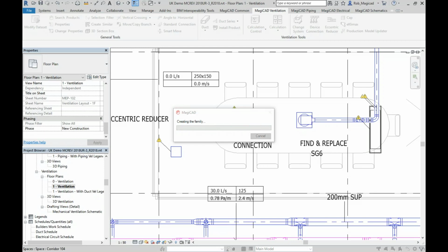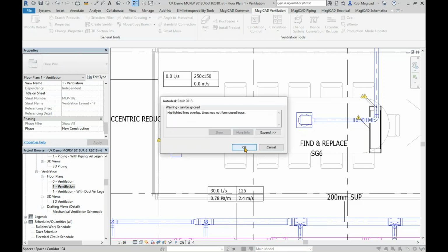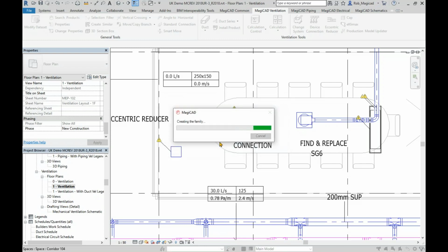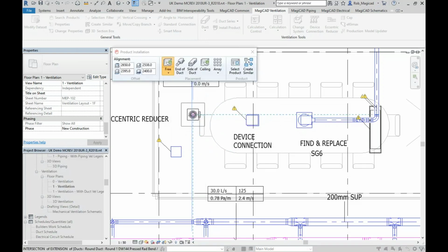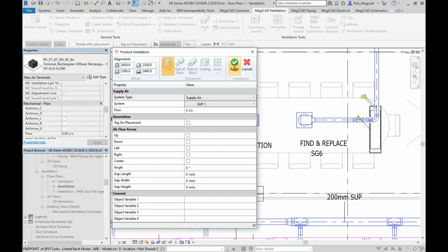You will need to use as well some kind of COBie plugin. So there's free ones available from Autodesk, like the COBie toolkit, and that actually allows you to set up a project for COBie use and COBie export. And if you want to export it to spreadsheets, you can. If you want to map parameters, you can.